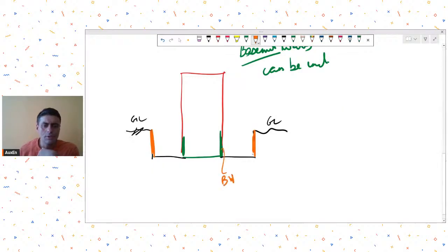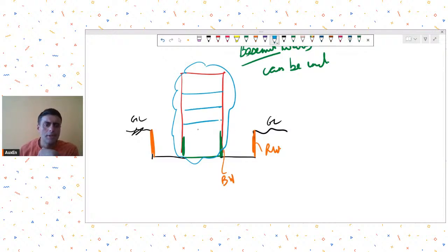So this is your basement wall, this is your retaining wall, let's say it's not connected with any horizontal element. Now in this case, your basement wall is not able to provide resistance to your base shear because there is no connecting podium. So because there is no connecting podium or horizontal slab, whatever resistance this basement wall provides will be as per the normal course in which it resists lateral loads.